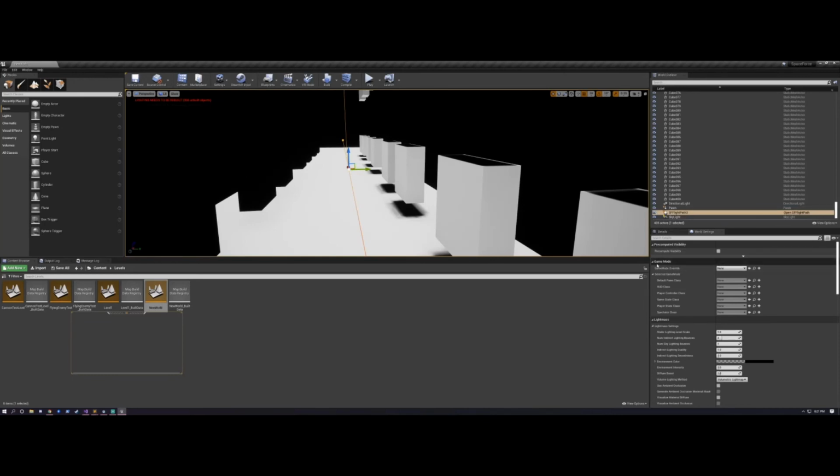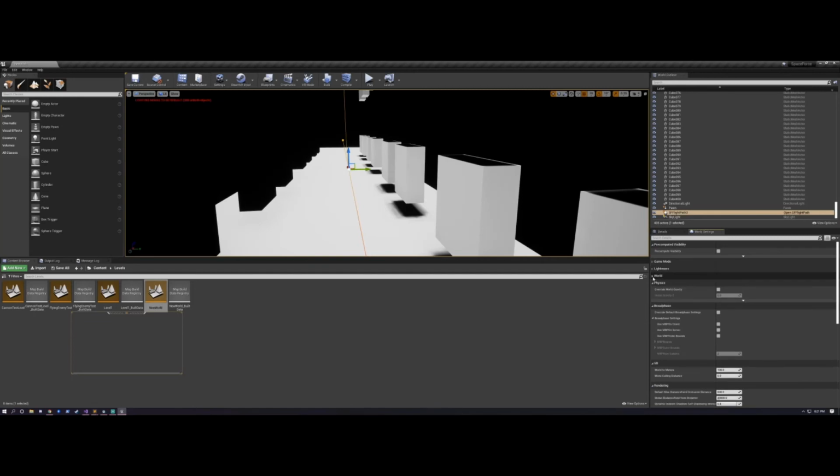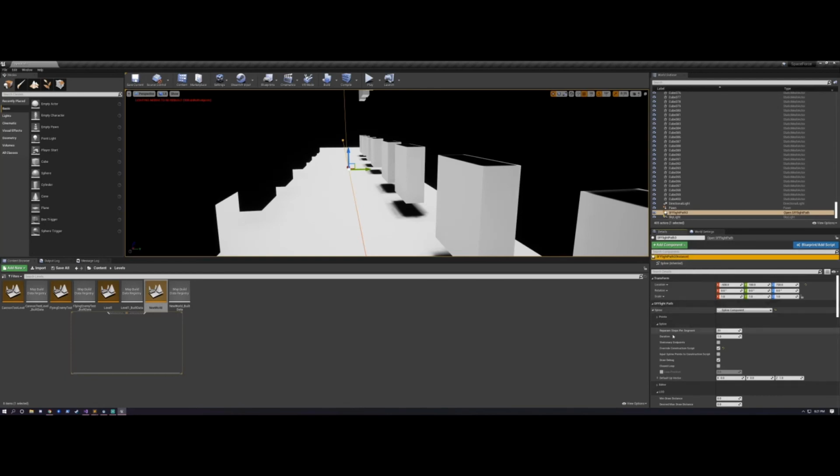I now was wondering, maybe there's just some setting that I haven't seen on my spline that helps me out with this. I mean, if it's a spline accuracy problem, it would be nice if they opened up some parameters for that. It turns out they do. So all this is like 2 days of debugging, I'd say. All this done for not really much reason, but I initially had not seen this. It's called reparm steps per segment. Number of steps per spline segment to place in the reparameterized table. That sounds to me like you're smoothing the table. It's a maximum between 10 and 100, which maybe is not enough for me, but this is steps per segment.